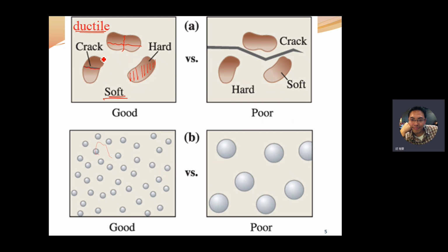You may ask whether the crack will propagate through the ductile matrix. It is quite unlikely, because those precipitates are brittle, so the crack initiates there first, and the matrix is quite ductile.